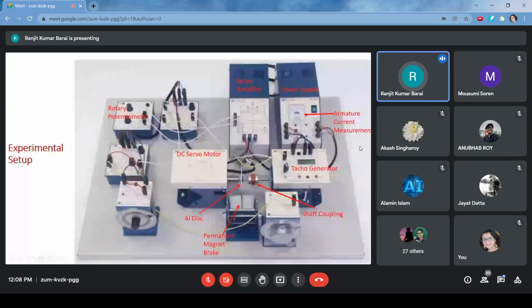Select some non-linear amplifier, what will happen? The control signal that is generated over here, its waveform will get distorted. If its waveform gets distorted, what will happen? The command that will appear at the input to the actuator will not be a proper control command, and the actuator will also malfunction, and the feedback control action will not be successful.